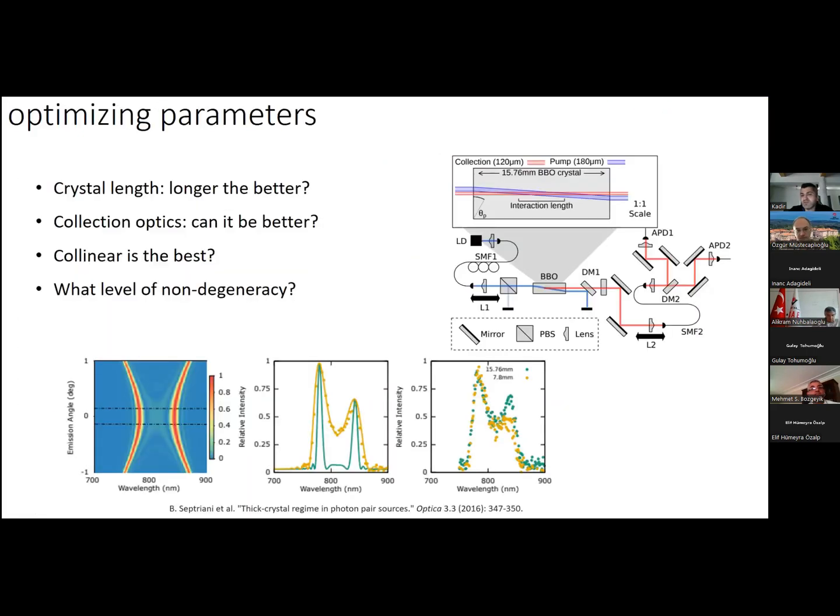Another thing is, for example, do we want to use fiber in the satellite or not? Because fibers are known to have birefringence depending on temperature drifts. If this is the Earth and the sun is here, the satellite takes 90 minutes to go around the Earth. So for 45 minutes, it's getting fried under the sunlight, and there is no atmosphere to block direct sunlight. Then for 45 minutes of eclipse, you have cold temperature. Therefore, you keep having this hot-cold cycle every 1.5 hours. This birefringence will kill all the entanglement that you have in your setup. Therefore, we decided not to use fibers.